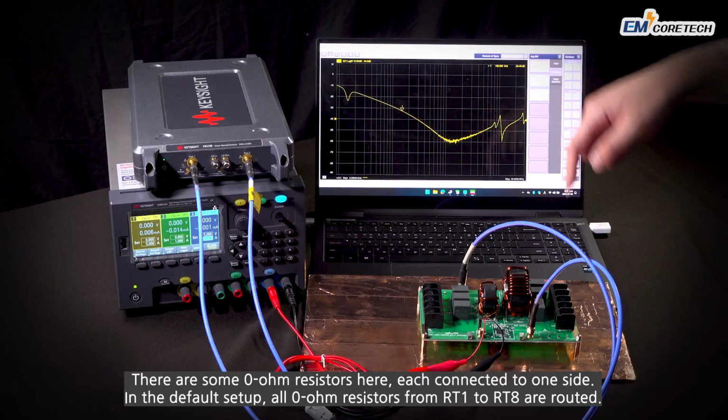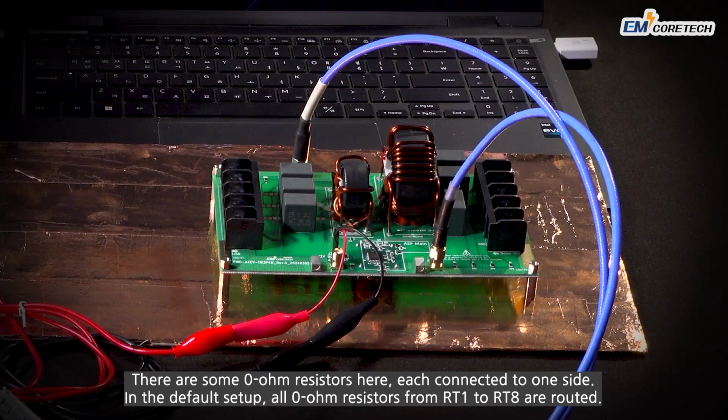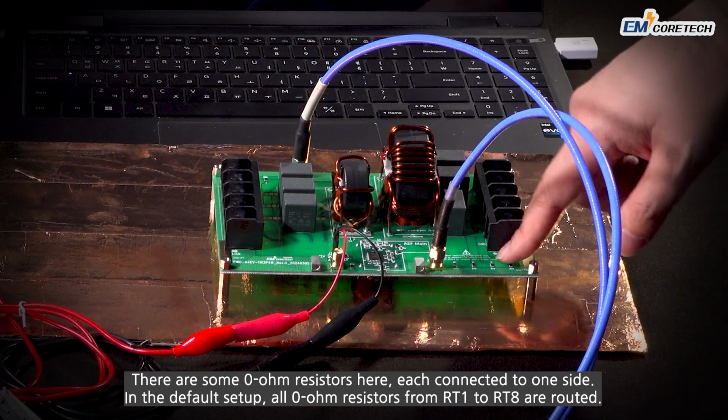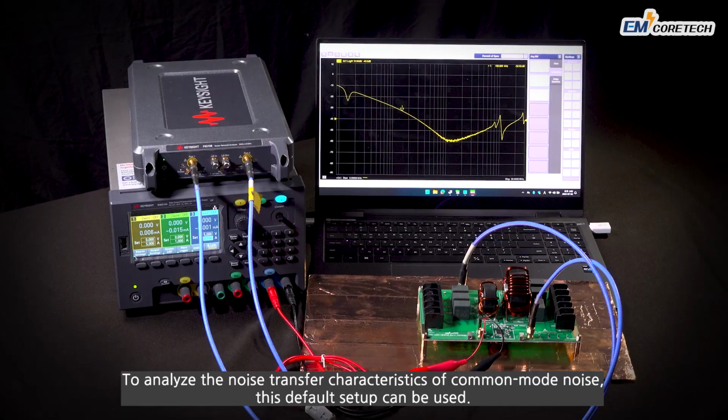There are some 0 ohm resistors here, each connected to one side. In the default setup, all 0 ohm resistors, from RD1 to RD8, are routed. To analyze the noise transfer characteristics of common mode noise, this default setup can be used.